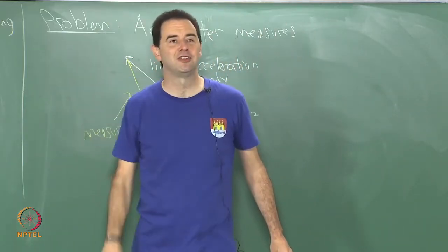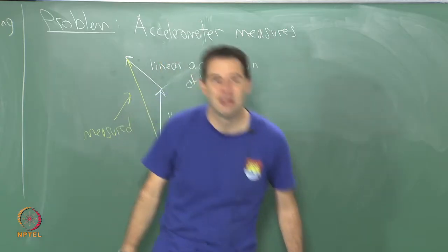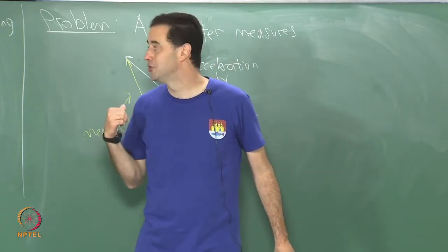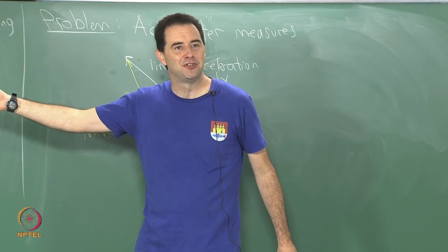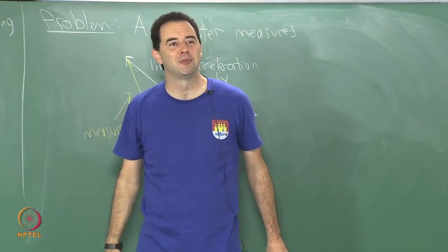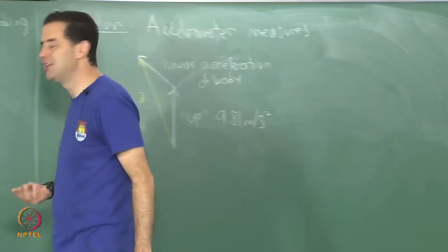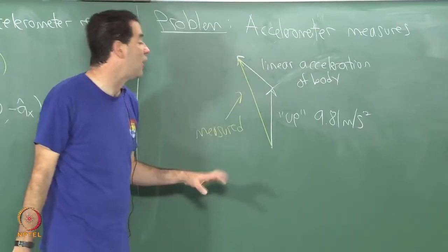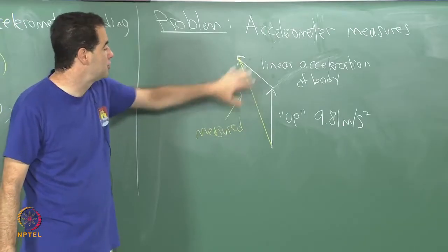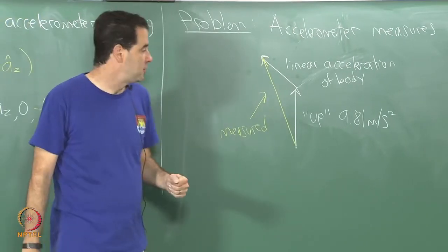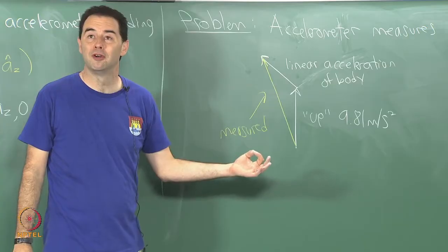But I can also linearly accelerate while doing that, and I should be able to get it so that I convince the drift correction system that makes this assumption that the world is tilted by a large amount. So you end up making some heuristics to try to separate out these two vectors so that you can get a reliable up reading. This particular assumption by itself won't work all the time.